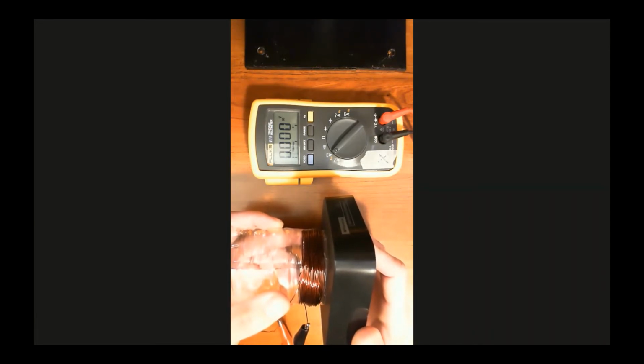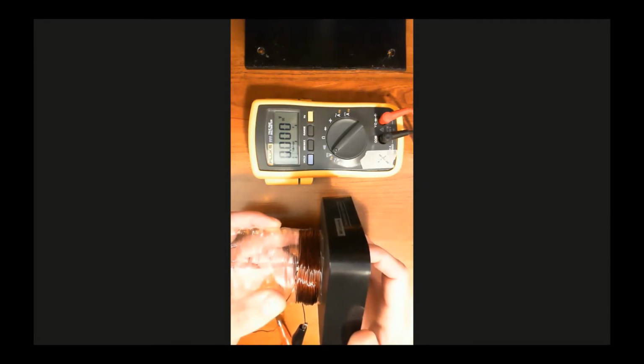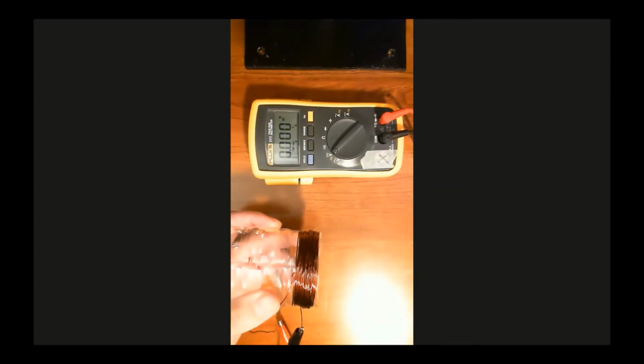I do have magnetic flux here, right? Because I've got that magnetic field coming from the magnet, and that magnetic field is going through the coil of wire. So it's not just the magnetic flux that creates the magnetic field. What we're going to say in a little bit is actually it's a change of magnetic flux going through the coil of wire that induces the voltage. So it has to be a changing magnetic flux. All right, so I can pull it apart. I saw negative 11 millivolts that time.